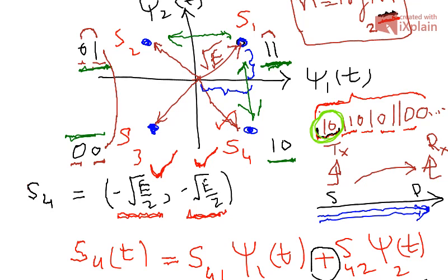Although the symbol carries 2 bits, both the bits are not in error, because each adjacent symbol differs by 1 bit. This is the importance of gray coding: when you have a gray coded mapping of bits to the symbols, for just one symbol error you have 1 bit error, for 2 symbol errors, 2 bit errors. So 2 symbols carry 4 bits in QPSK, but if 2 symbols are in error, we would not get 4 bits in error, we would get just 2 bits in error.